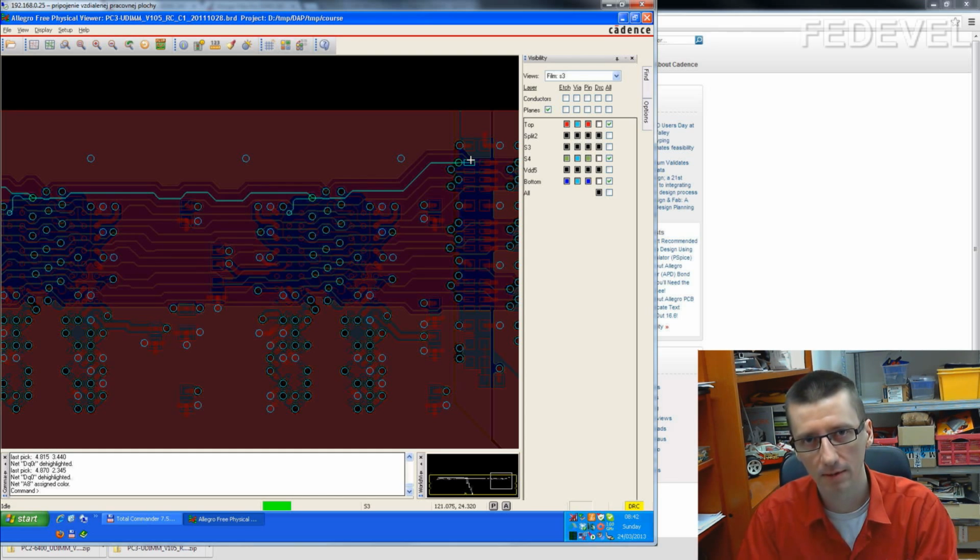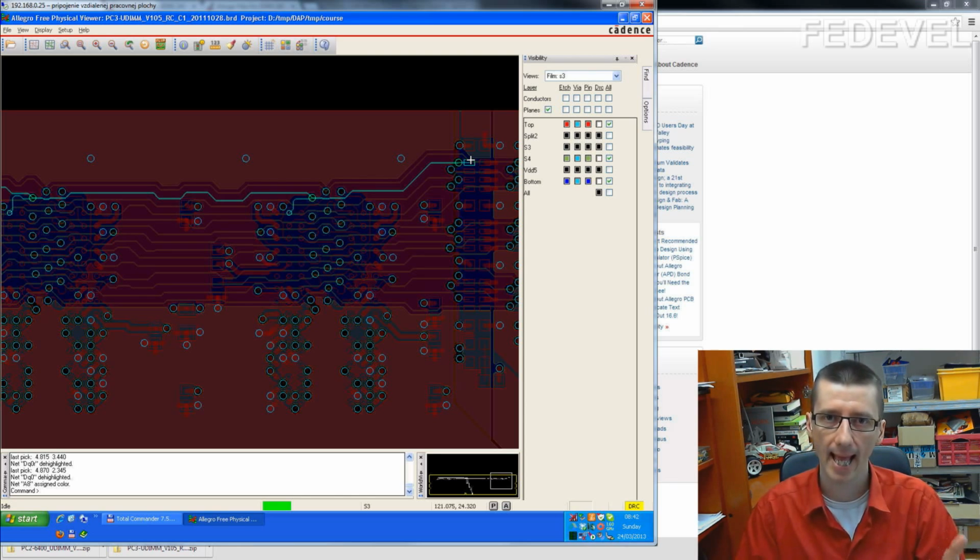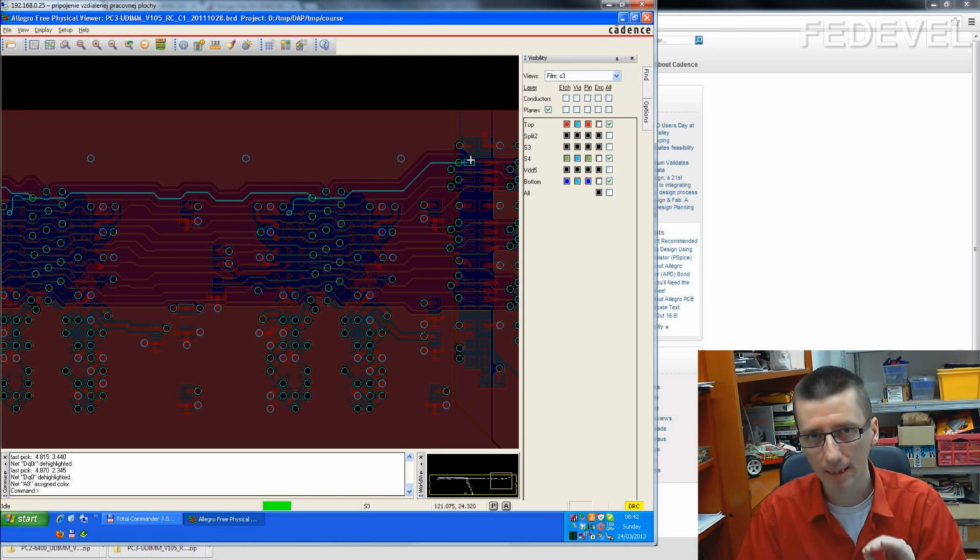So it's completely different. But in the schematic, it is a connection of the A8 signal to all four memory chips. The connection is almost the same in the schematic between DDR2 and DDR3, between this T-branch topology and flyby topology. But as you can see in layout, it is completely different. It works in a completely different way. So be very careful, read the design guide.